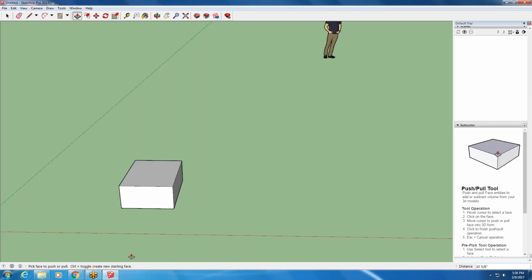So this is very similar to our command line, right? So I want you to get in use of this as it is like AutoCAD so that you're not feeling too uncomfortable in this environment. This is our command line down here. It's prompting me kind of what tool I'm using, how to use it. Over here I can see the distance that was push-pulled up, and then I have my main home that I can go to for all of my tools in the upper left-hand corner.